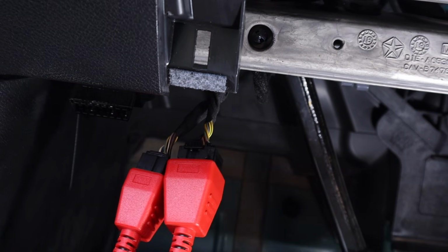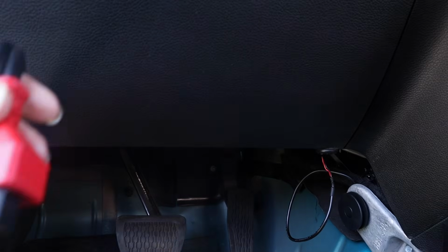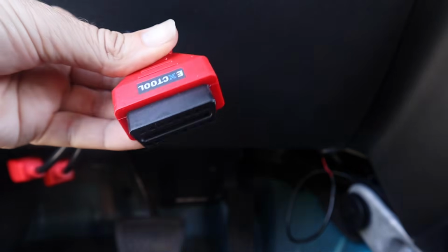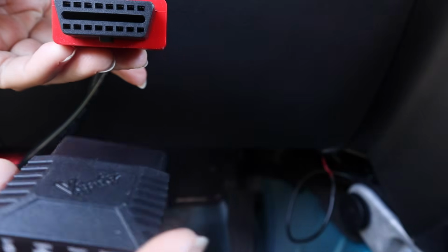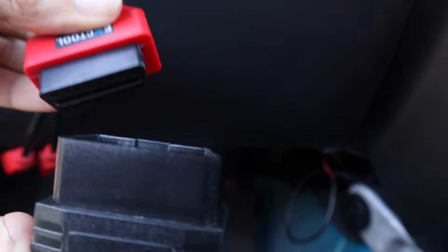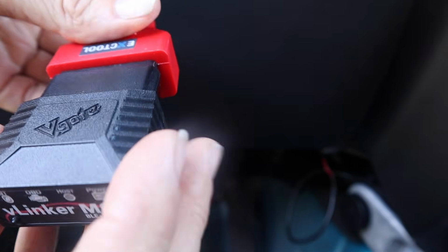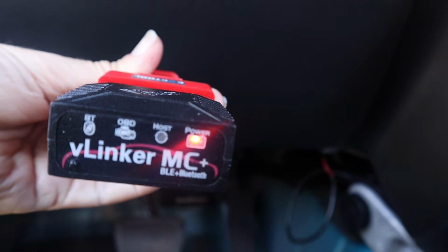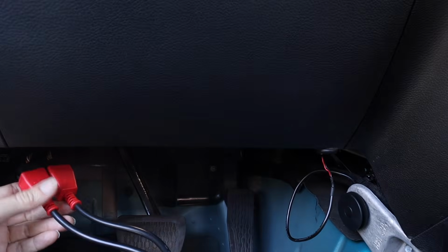Okay, and then the last step really of our hardware install is to connect the OBD dongle to this. Now I did try to connect the OBD dongle to the actual OBD port, but I think because of the security gateway measures, it just wouldn't let me, it wouldn't work quite right. Nevertheless, just to get it to work, we connect our OBD dongle to the OBD connection here, and you can see it'll start lighting up, which means it's getting power, and then we're pretty much good to go.